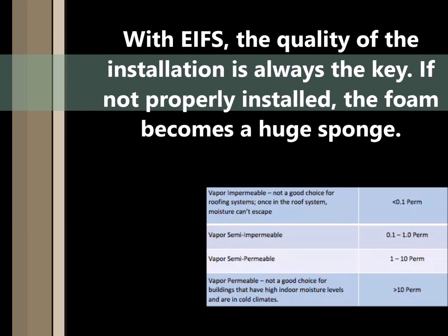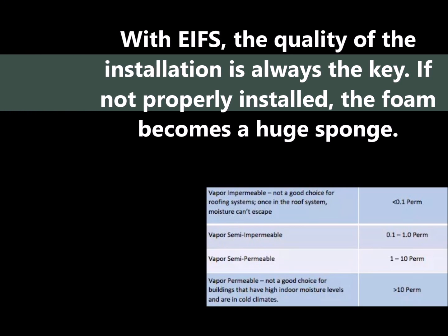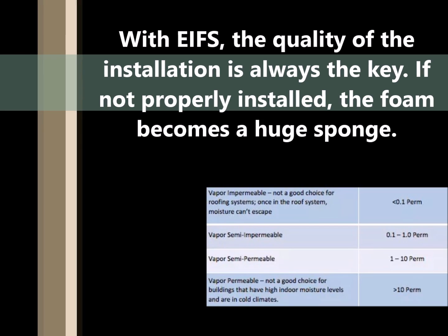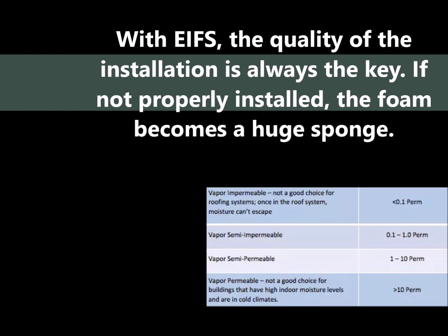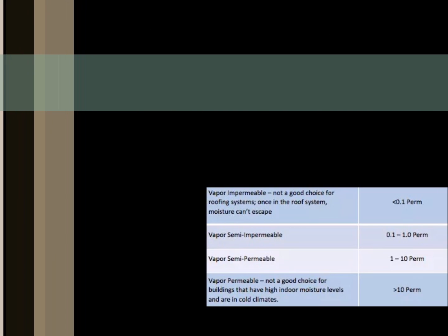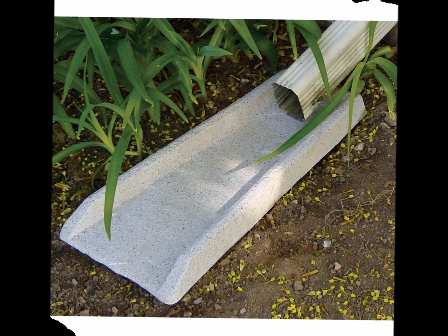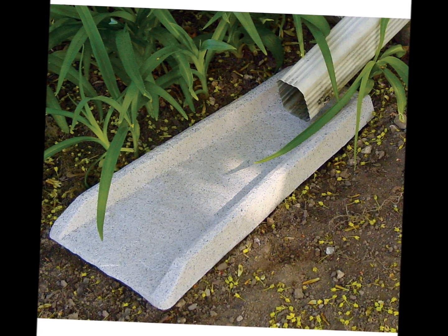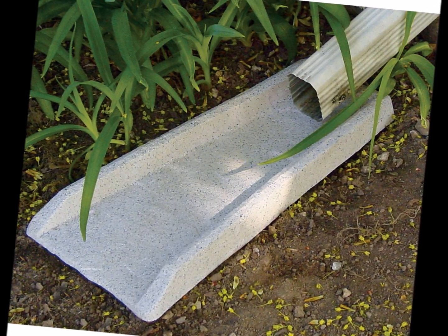Because of the foundation's porous nature, moisture can also wick up from the ground. If the downspout is near the foundation, water is wicking up from the foundation wall. Colder temperatures are on the exterior. The building must be able to shed water and manage water away from the foundation and structure. A simple thing like diverting downspouts is essential. Lots of times there's missing splash blocks.